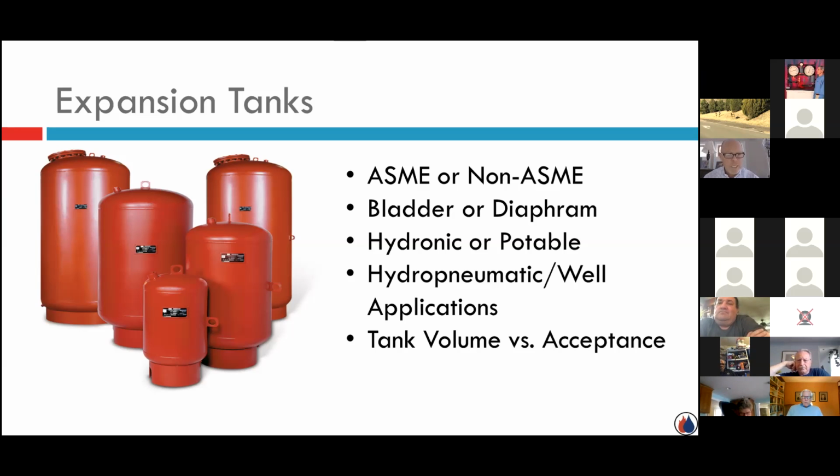Well, they eventually made a decision saying, hey, we don't want that water. Once it's in your house, we don't want it back in the street. And so they installed these backflow preventers, these check valves. And all of a sudden, they were getting complaints of relief valves popping on these water heaters. And as it turned out, they needed to start adding these potable expansion tanks to accept that expanded water.